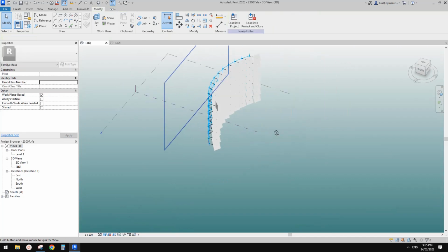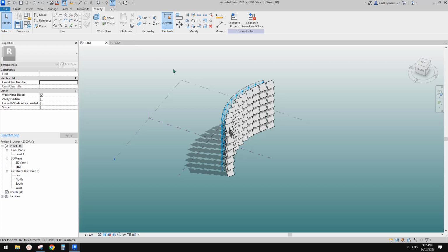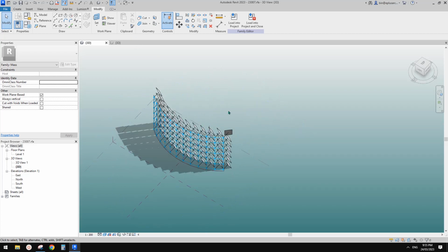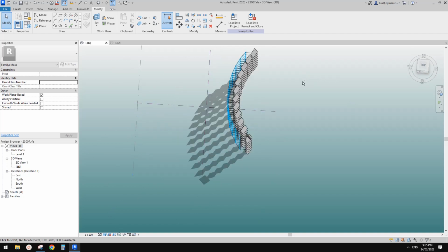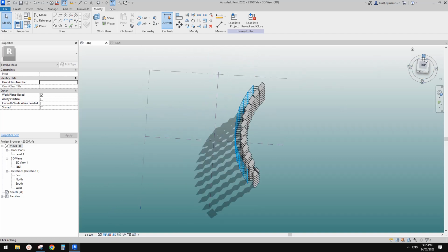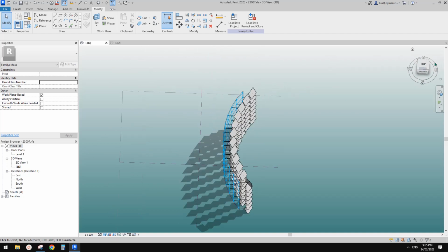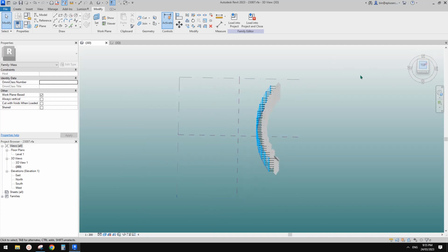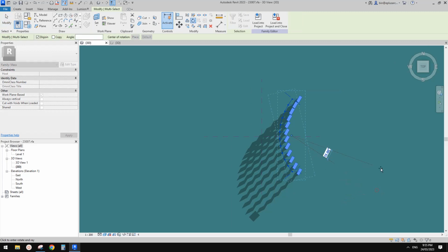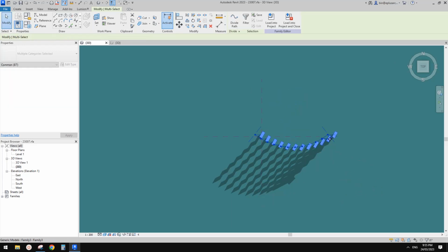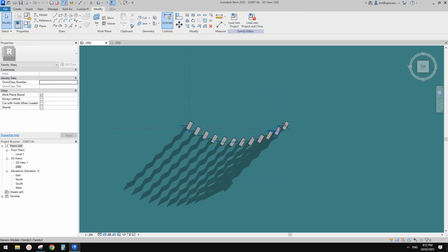And now, before we start to use Dynamo, I want to do one more thing. Usually, southern hemisphere, so the sun's always in the north direction. So I'm going to just select everything here and rotate, RO, rotate them by 90 degrees. Okay, so it will make more sense.